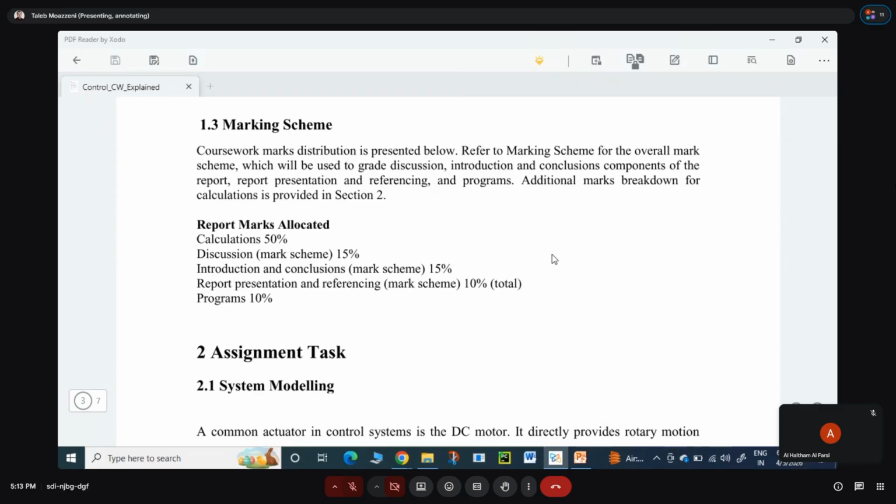You change these parameters for the PID controller. What happens to the output? You should show me at least two plots, the more the better, and compare them and talk about the effect of these parameters on the output. For example, you say, if I increase Kp, I see in figure 2 that the overshoot comes down.